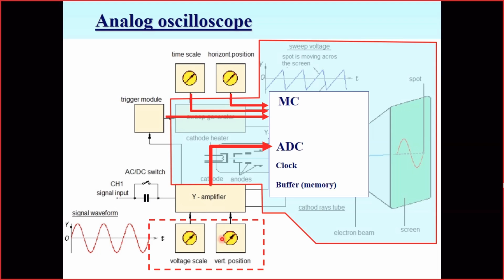With the vertical position, there may be different solutions, different ways to design how to provide it. We may add it to an already converted digital signal. But generally, it's better to add the vertical position to the input voltage, because we may correct the input voltage a little bit without losing data during the digitization of signals that occupy a wrong range. So we could use this vertical position change in analog form and add it to the output of the amplifier.